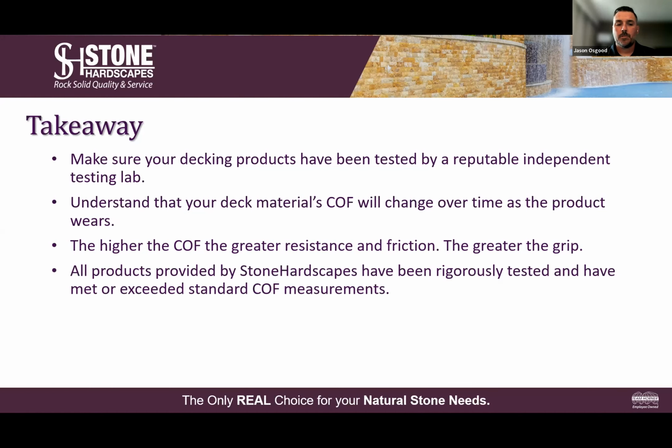And I said this before, every decking material that we sell has been rigorously tested and has met or exceeded standard coefficient of friction measurements. All of our material has passed the older standard, the ASTM C1028, and all the newer products are passing the ANSI A137.1.